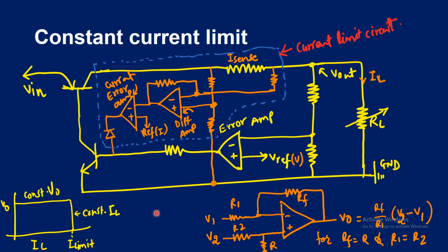Before that, I would like to point out that the maximum current that a linear regulator can supply to the load is specified on the datasheet. Many regulators, including LDO, low dropout voltage regulators, specify only a single value of maximum load current. And that value is guaranteed for any input output voltage within the maximum ratings of that part. So you refer to the datasheet and you see the voltage inputs and outputs, and there will be a single value of maximum load current for that part.